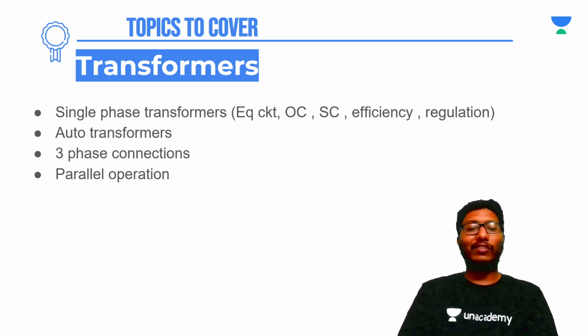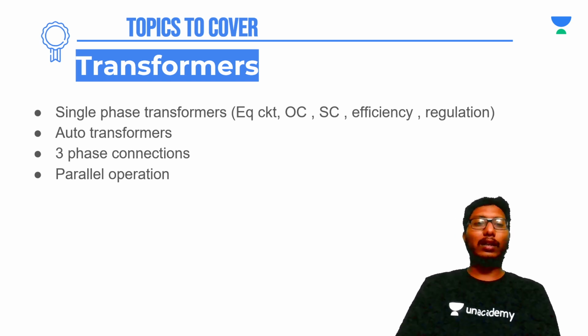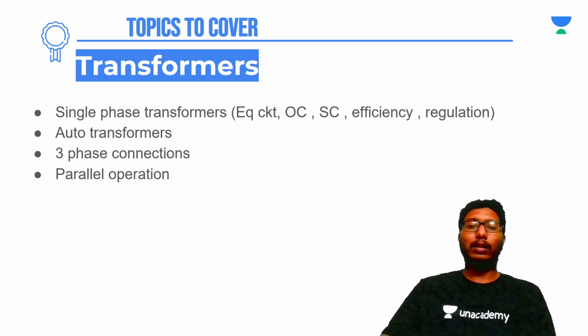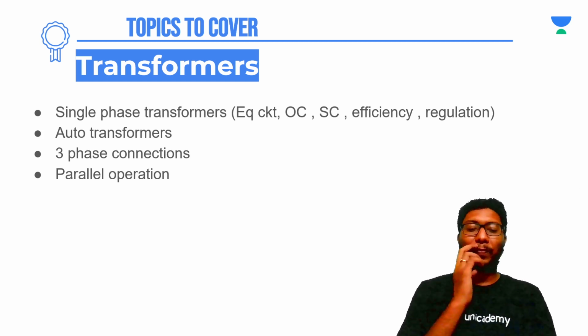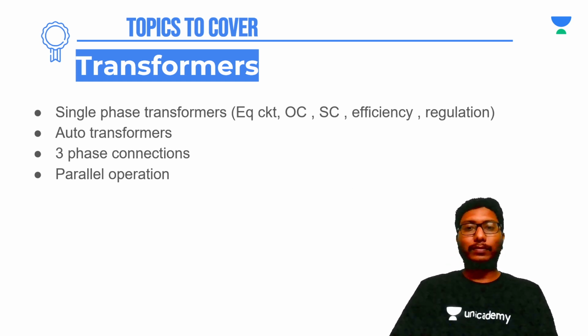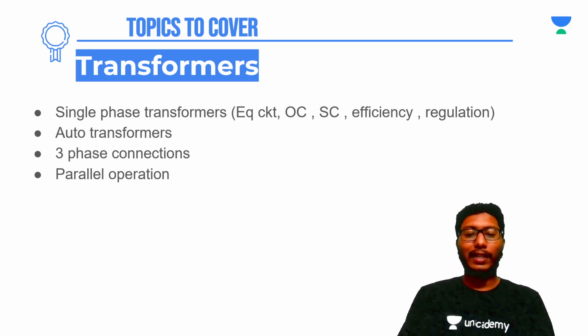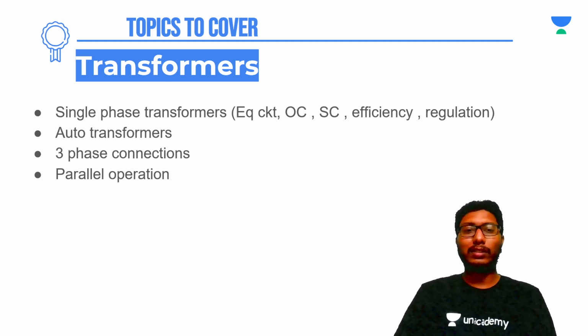So now coming to three-phase transformers. Three-phase transformers are divided into many groups, but the most important connections are delta delta, y delta, delta y, and y y. If a transformer diagram is given, you should be able to draw the vectorial diagrams, and know at what angle secondary is lagging and at what angle the primary is leading, by drawing these vectorial diagrams of three-phase connections.